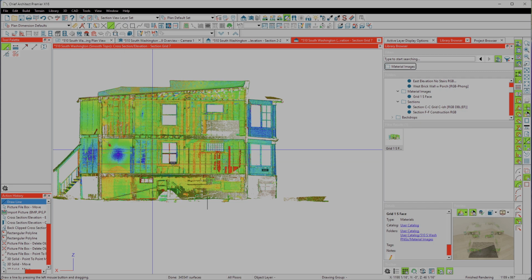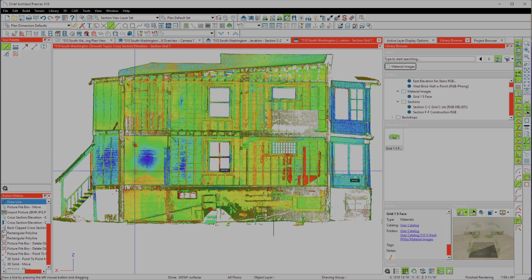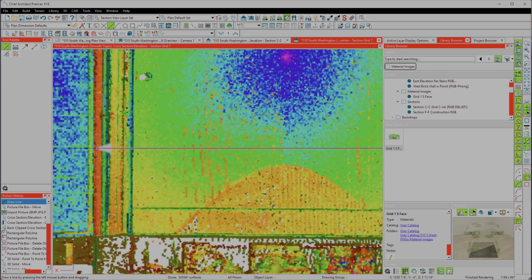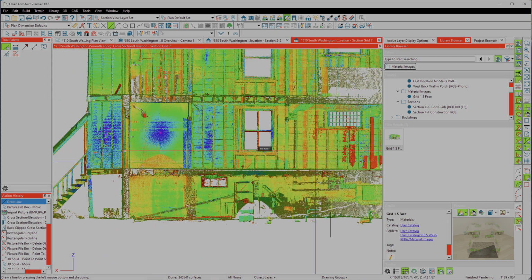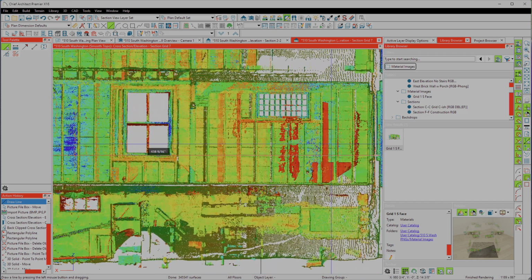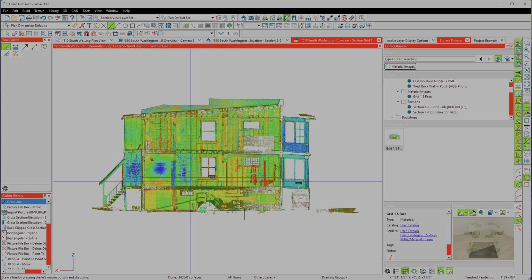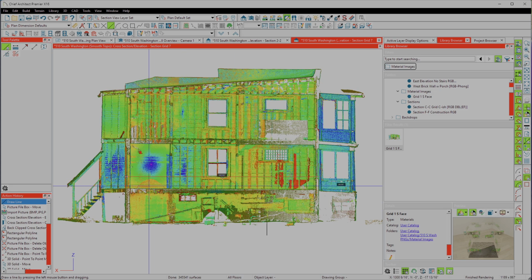Now there's ways to do this in ReCap where I can set the X and get a perfectly horizontal one, but this actually works pretty good. It'll be slightly off by the amount of drop over that long distance, but just use the X feature to draw dimensions and you'll get it more exact. I don't want to go through the trouble of creating one right at this moment, because I just need to get this particular thing done.